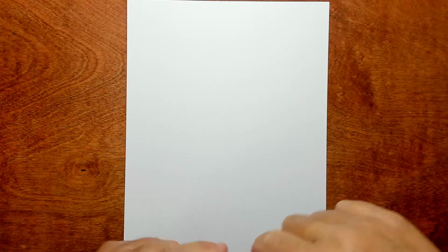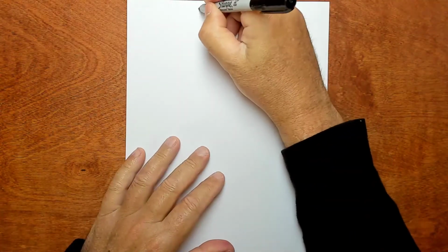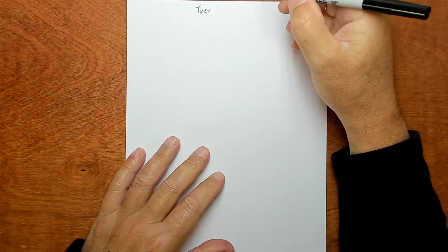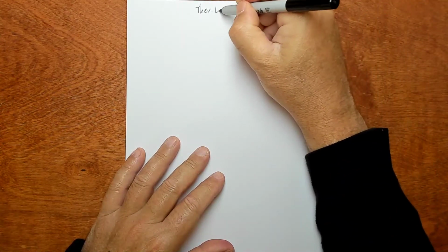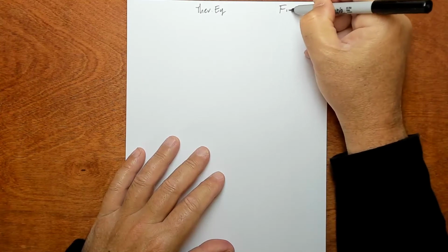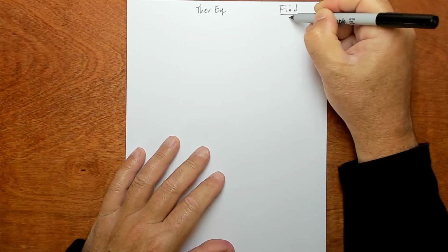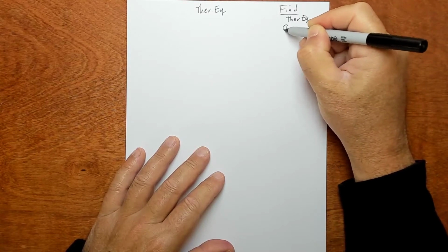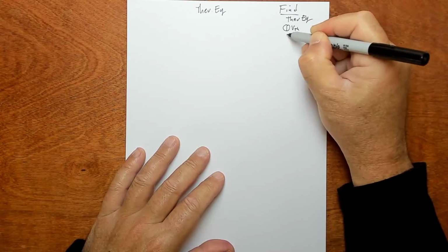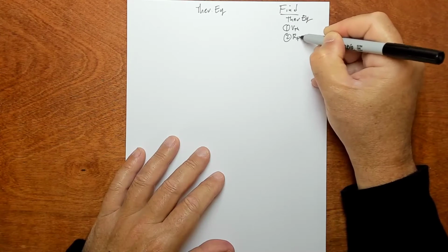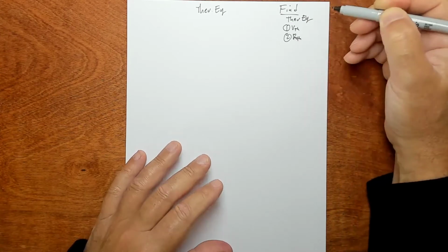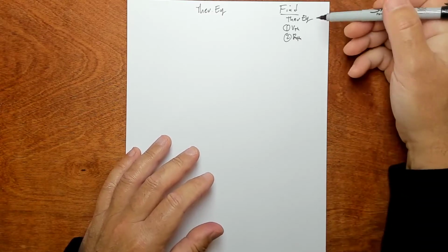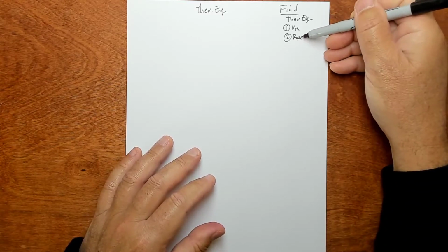Welcome back. Let's do another Thevenin equivalent, and this time we're going to use node voltage method to find V sub Thevenin. Okay, so we want to find the Thevenin equivalent circuit, and there's two steps. Step 1, we find V sub Thevenin, and step 2, we find R sub Thevenin. So unless you're using source transforms all the way through, then there's going to be these two steps.